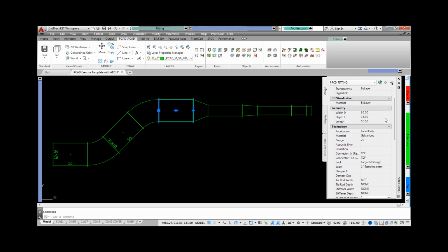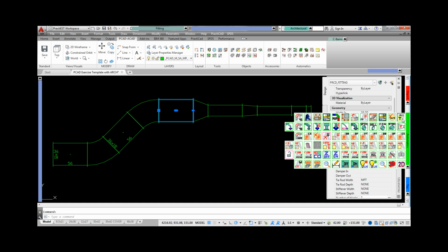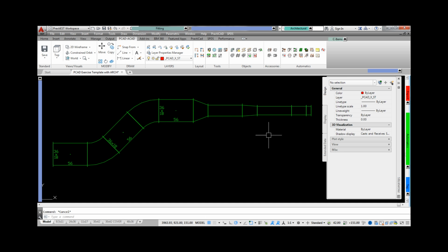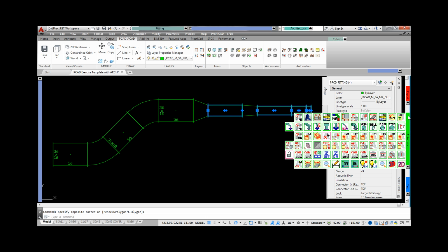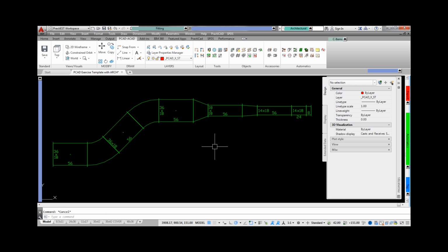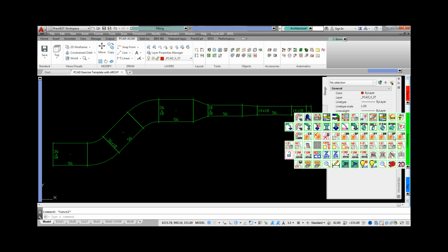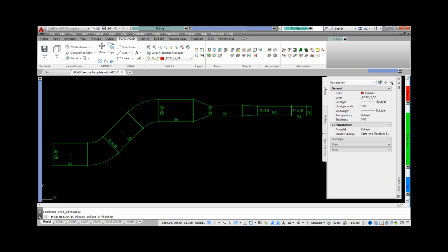Looking at another important variable, we will demonstrate changes in size. Look here at the duct line. Notice each fitting is getting smaller than the next. When the PractiCAD tagging automatic is triggered, it searches the fittings for their sizes and chooses the exact tag we want in the exact place we need. You can see how the W by D tags and the length tags are changing and moving inside and outside of the duct to accommodate for these differences. Even when we decide to run a piece numbering automatic, the software places them neat and cleanly on the drawing exactly where the user wants them.